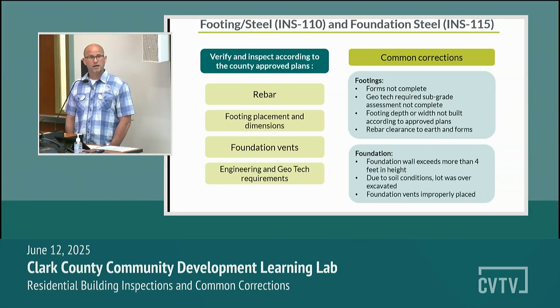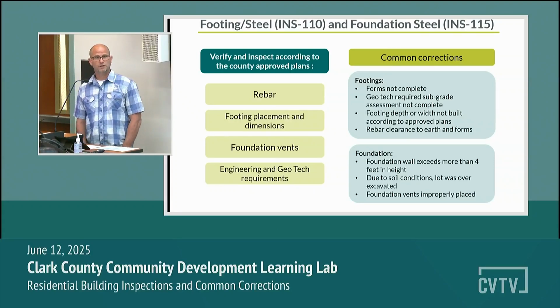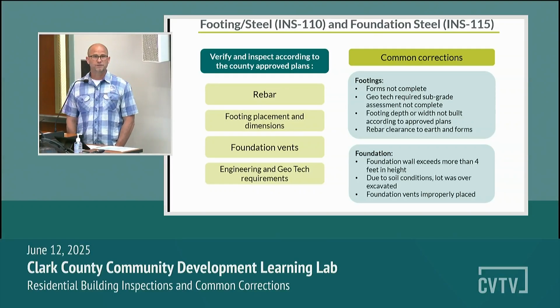Now, depending on how far down you have to dig to get to your foundation level, they might need to come out again and check. So what they'll say a lot of times on their report is, after excavation, but prior to pouring, they want to come back out and look again. They want to see if there's any organic material that's down there, a big old tree stump or something that needs to be removed, or some soil that nobody knew about 4 feet down that needs to be removed. So they're going to need to come out, do an inspection, write together a report, and that's going to be required to be done prior to pouring any concrete.